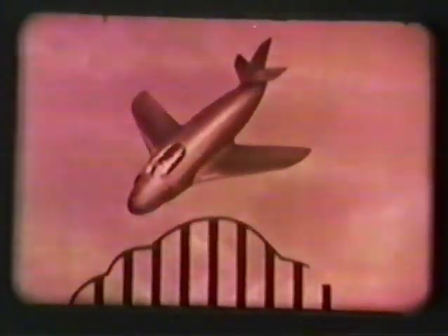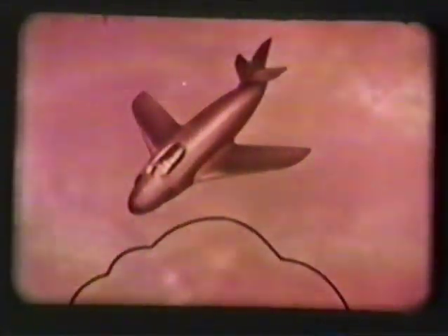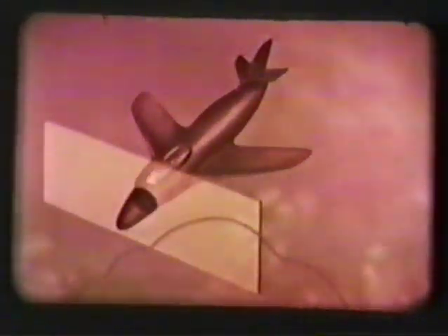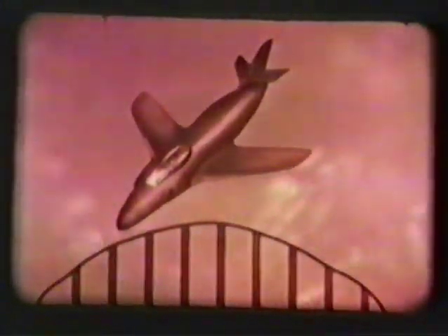The resulting curve is irregular. Let us redesign the aircraft to smooth out the bumps in the curve so that the cross-section area changes gradually and not abruptly. So instead of the curve with bumps, a much smoother curve is obtained.